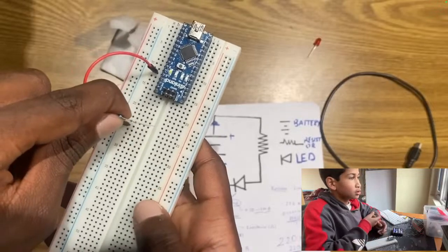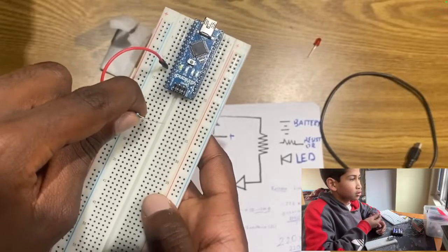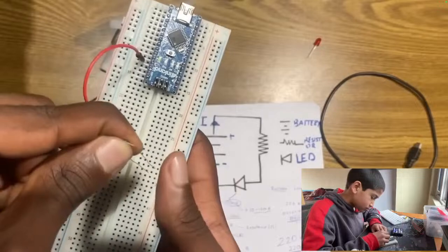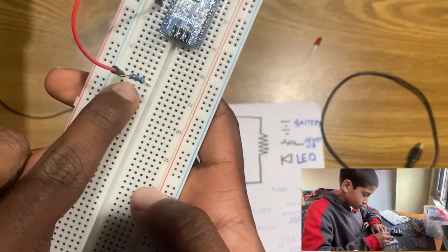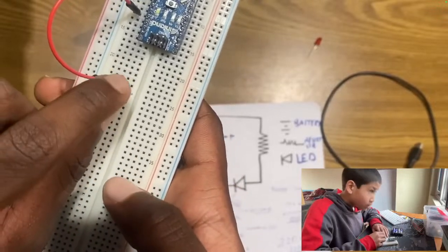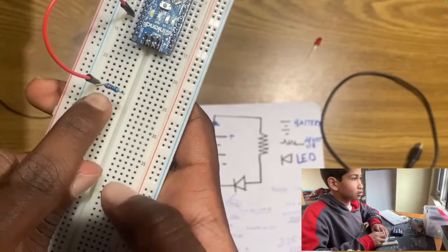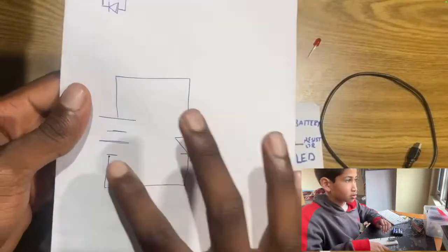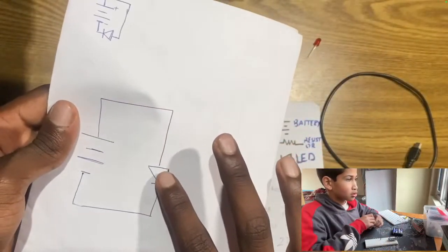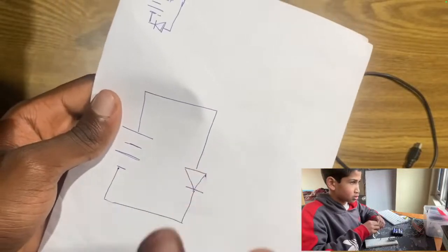So if I connected it, let's say, in the same row, horizontally in the same row. Let me just make this a bit more thin. Let's say I connected it this way, okay? If the resistor is not connected properly, sometimes this happens, you have to push it in. And if the resistor is not connected properly, what is going to happen is basically this type of circuit. We have our Arduino right here and directly connected to what? To our LED. So it's going to fry our LED.